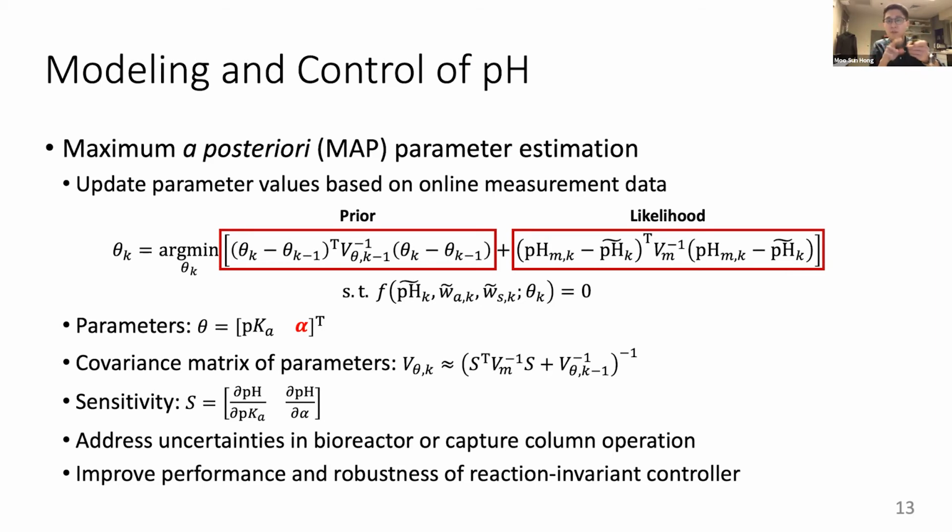This is one of the reasons why we had the programmable logic controller connected to the computer in the system. The reason we use the PLC for the low-level control is that it's very, very stable and it's industry standard, so it will never fail during the run. But because of its simplicity, it doesn't have the computation power to perform optimization at each of the time points. So for that, we use the computer for the actual optimization or the parameter estimation, but we feed the information back to the PLC. So the PLC actually performs the optimal control at each of the time points.